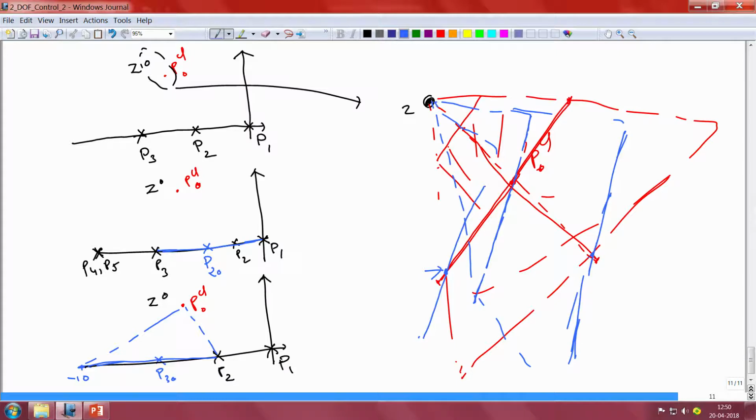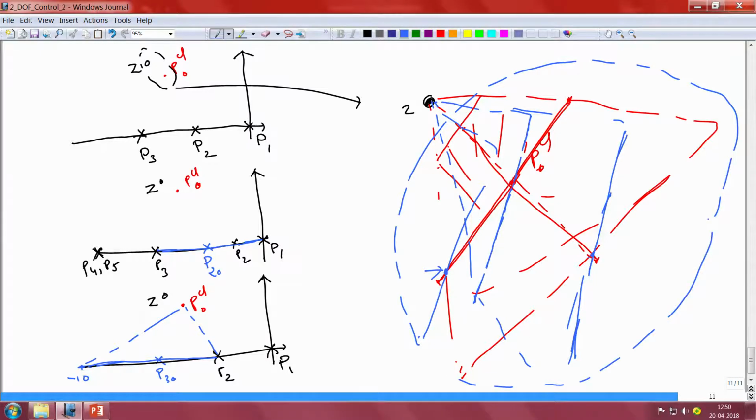So, what we essentially do therefore is we consider the variation of one parameter at a time and determine the curve along which the closed loop pole would vary when this particular parameter varies, and then we subsequently allow for the second parameter to vary and then the third parameter to vary, and finally determine the entire overall region in which the closed loop pole can possibly vary when one or more of these parameters change.